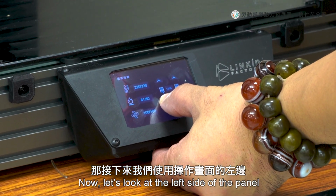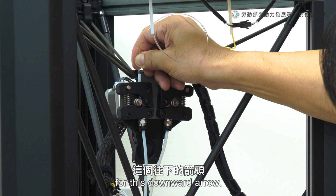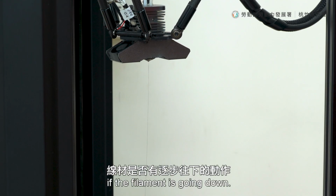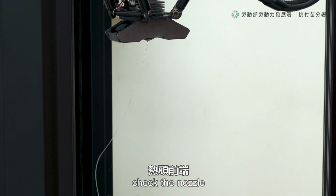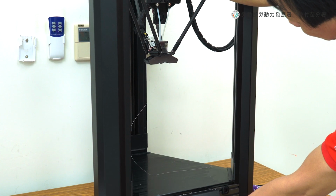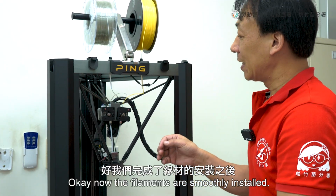Now look back at the control panel for this downward arrow. Meanwhile, feel with your right hand if the filament is going down. Again, check the nozzle to see if the supporting filament is going smoothly. If it is, then no problem. Okay, now the filaments are installed.